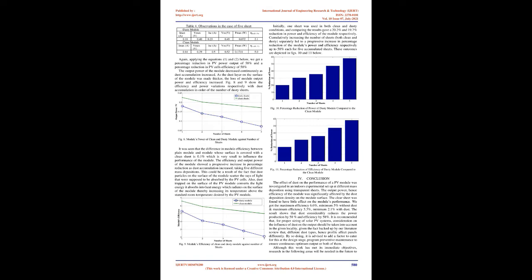3. Results and discussion. Here, the results obtained in the experiments carried out as described above are presented and discussed. The voltmeter reading using the solar pyranometer was 170 mV corresponding to an irradiance of 170 W/m². With the module's cell occupied area, Ac, of 0.02 square meters, the input power is calculated as P = 170.2 × 0.02 = 3.4 W. This power is the same throughout this experiment since the cell's area and the irradiance are kept constant.